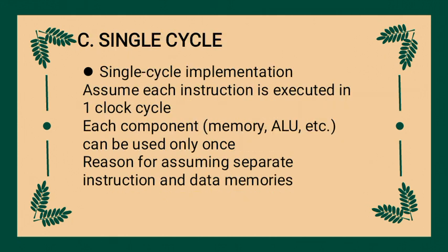C. Single cycle. Single cycle implementation assumes each instruction is executed in one clock cycle. Each component, memory, ALU, etc., can be used only once. Reason for assuming separate instruction and data memories.